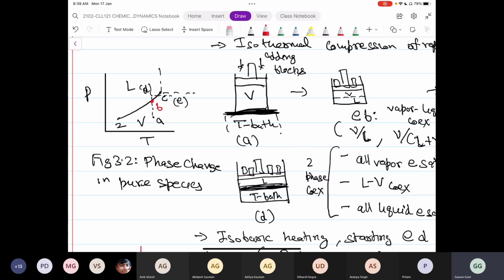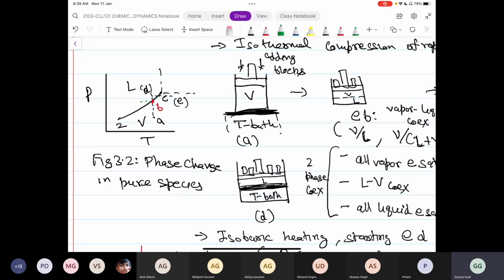And you can clearly see here that this curve a priori tells you, if I have saturated liquid, let's say saturated water at 1 bar, all you will do is draw a horizontal line at 1 bar and find out where it intersects with this curve. Wherever it intersects the curve, you will then be able to calculate the temperature.